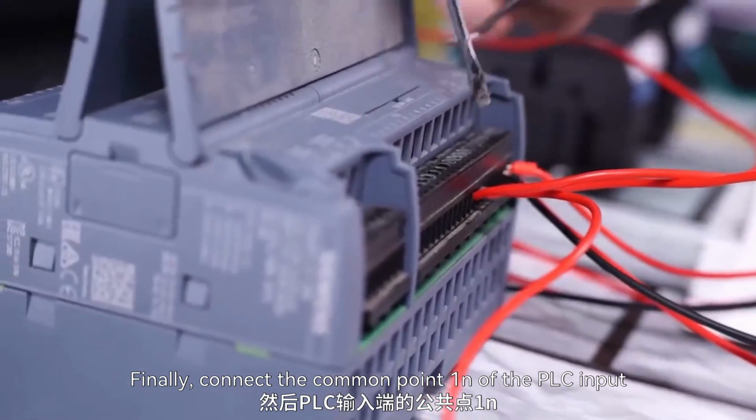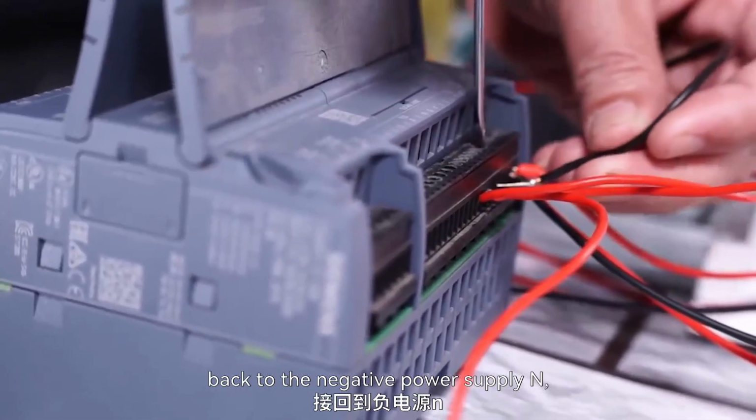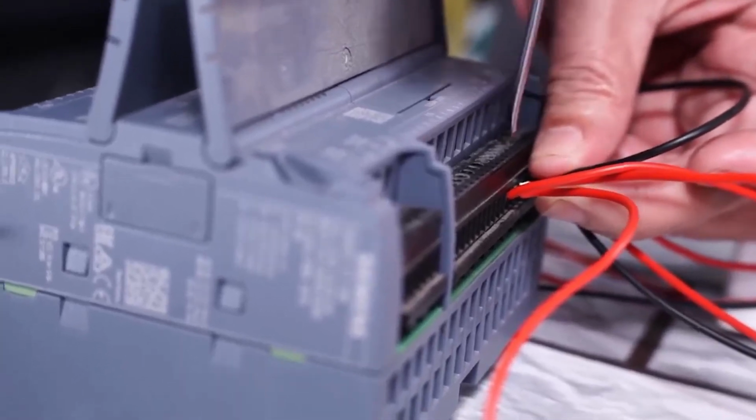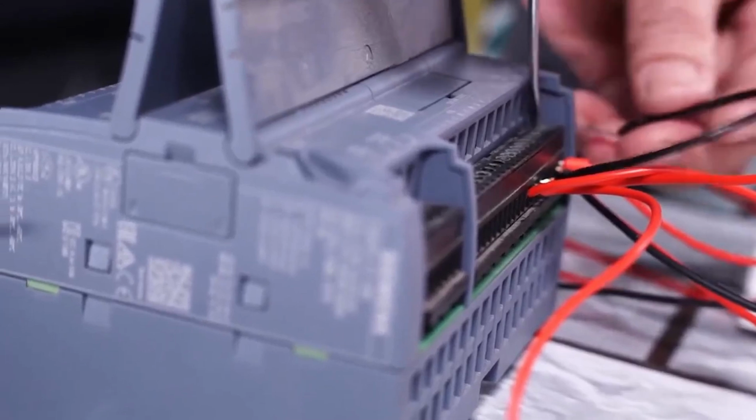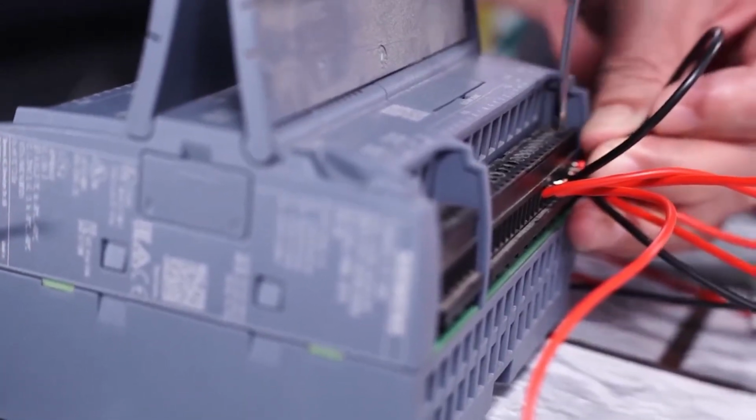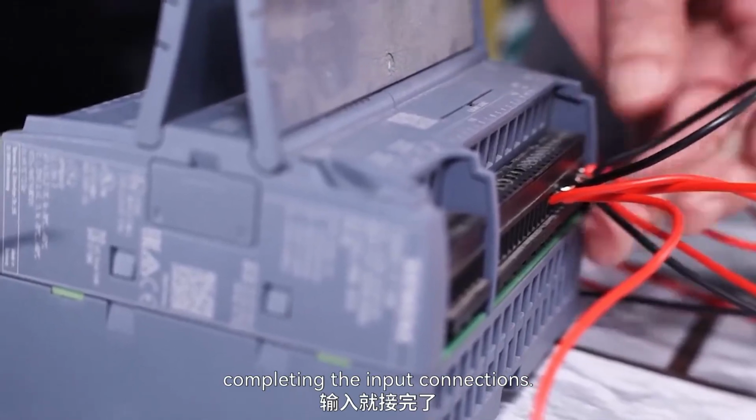Finally, connect the common point 1 end of the PLC input back to the negative power supply end, completing the input connections.